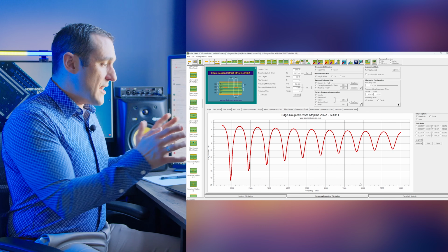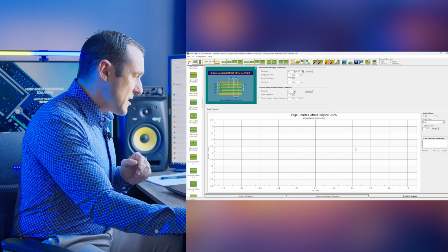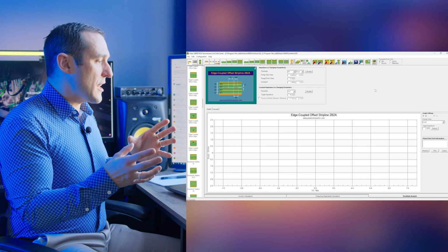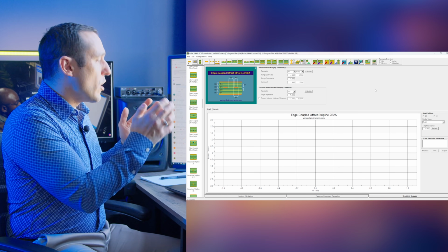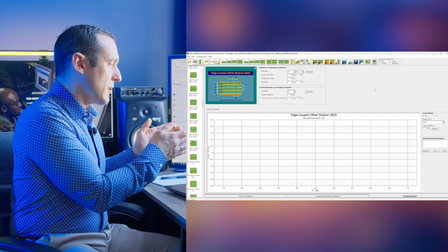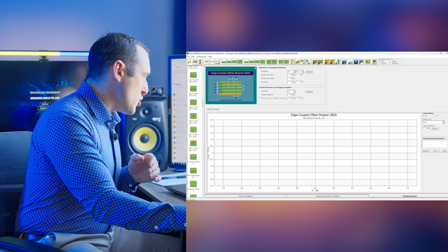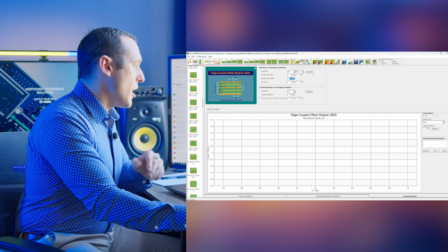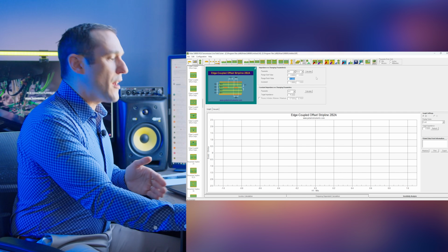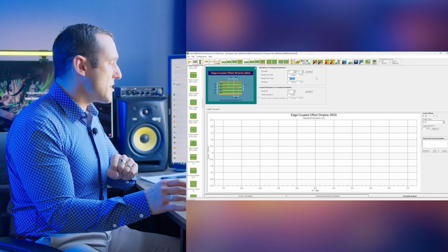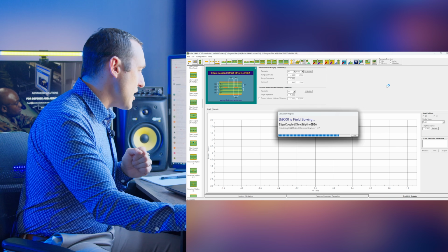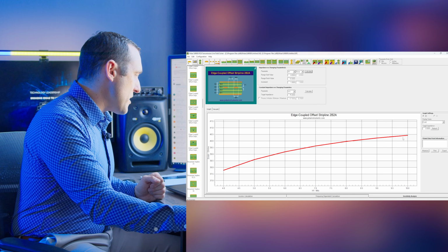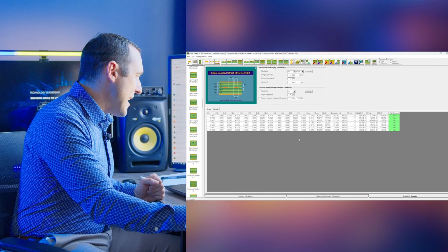The other thing that you can do in SI9000 is sensitivity analysis. And sensitivity analysis is really useful because it shows you how your interconnect changes as you modify one of the parameters in this interconnect model. So for example, if I were to change, let's say the substrate thickness from 4 mil to 10 mil, and then I hold all other parameters constant, it will then tell me how does the odd mode impedance of one of these traces in this model change. So you can see here, if I just hit calculate, it's going to go through and run all of those calculations, and then it shows me that result both as a graph as well as in the table.